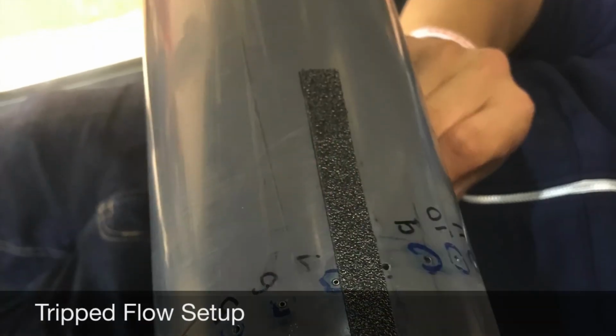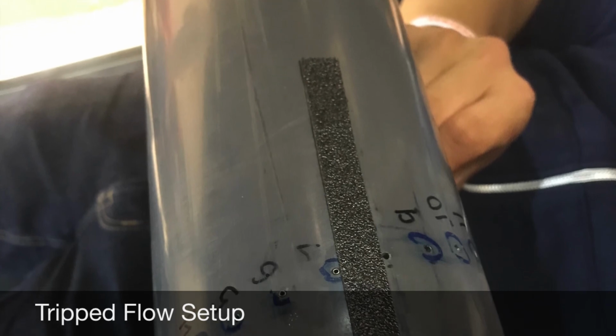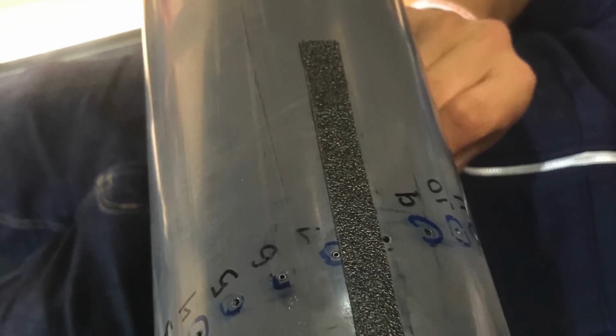After every RPM increment, LabView was used to observe the change of velocity, ensuring that the wind tunnel reached a steady state before recording the data. In addition, a video of the flow at each RPM setting was recorded in real time and in slow motion in order to use the results later. After all the data was collected, the wind tunnel was slowed down and then turned off.